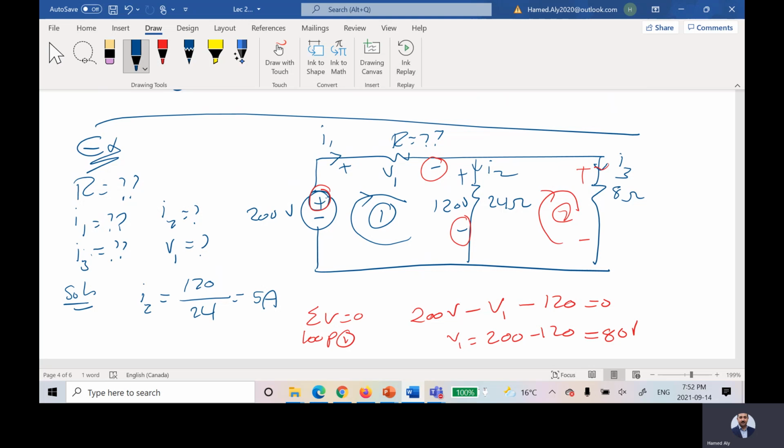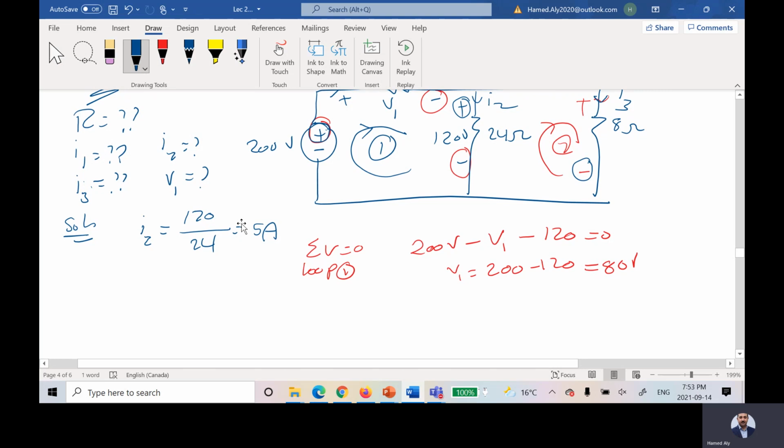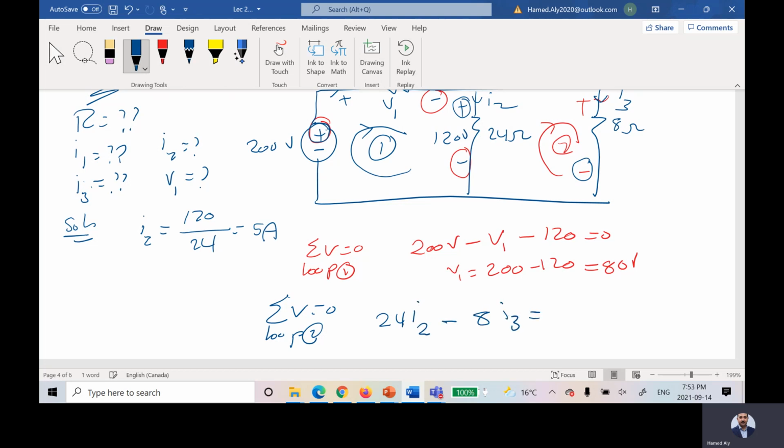So the second sign, my friend, what's your name? Mo? Okay, Mo, right now, I'm rotating in this loop and I'm keeping the second sign. The second sign for 24. Yes. And the second sign for 8. Yes. You got what I would like you to know. So right now, I would like to say summation V is equal to 0 for loop number 2. So 24 times I2 minus 8 times I3 is equal to 0.